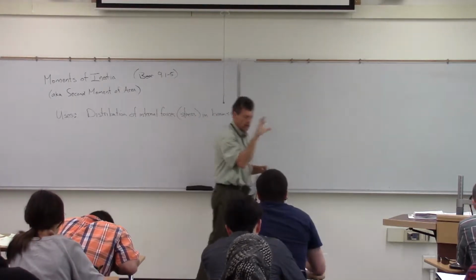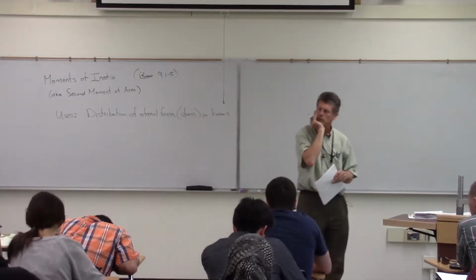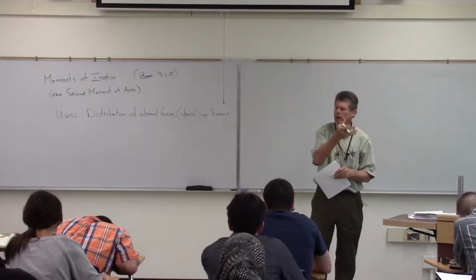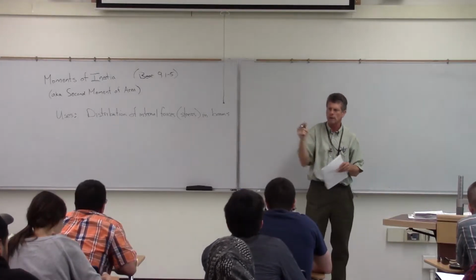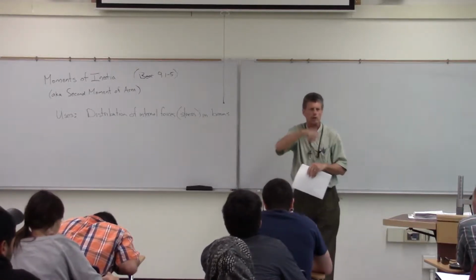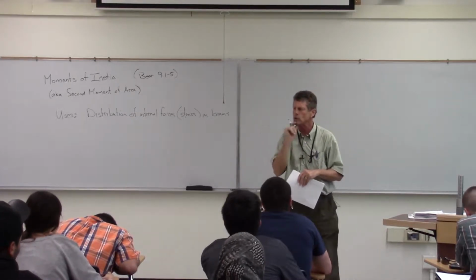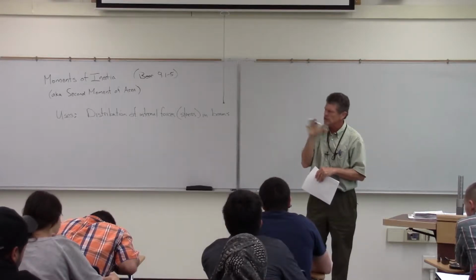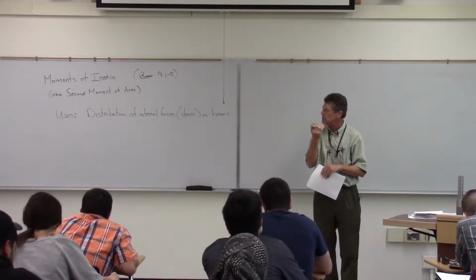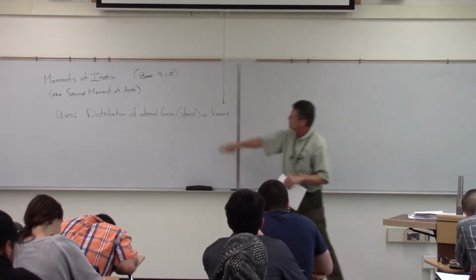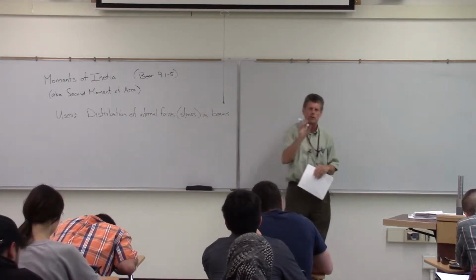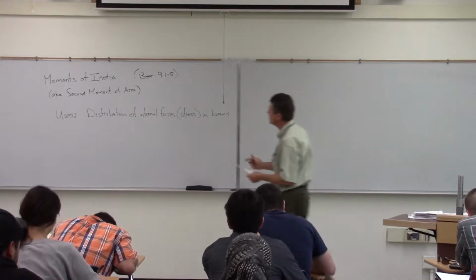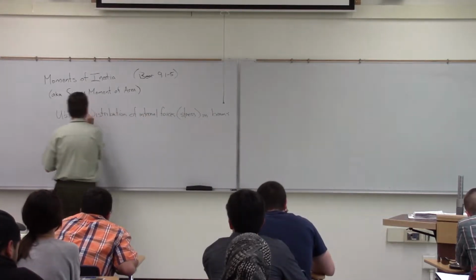is we're going to be talking about how this internal force is distributed across the beam. Because right now, remember, when we cut a beam open and we look at it internally, we get a couple of straight forces, a vertical force there, our shear force, an axial force, and then this curlicue thing. Well, that doesn't necessarily describe everything. When we get into mechanics of materials, we're going to be looking at what we call stress, basically a distribution of that force across the section there. So it's used for that.